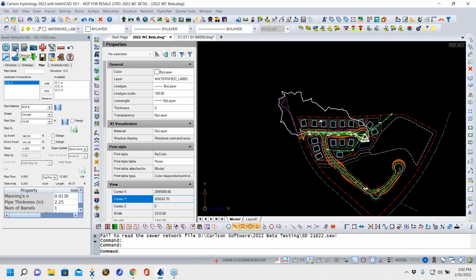Now up here at the top, you can see I could tell the program to design my sanitary sewer. Now, you see why I wasn't worried about inverts. I could care less about inverts. I just pick, pick, pick, pick, tell it the type of inlet, the structure, the drainage areas, and start off with your first pipe size being 15-inch or whatever the minimum is, and everything else falls into place accordingly.